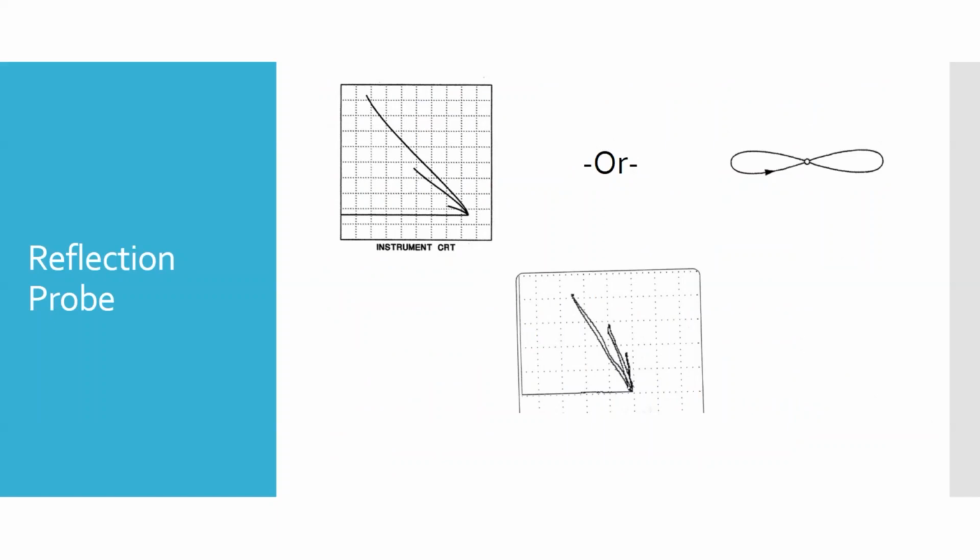And that's why we use a reference standard. So before you go test your airplane, before you go test your wheel, before you do your fuselage skin to check for cracks around rivets, before you look for cracks in the bead seat of the wheel, you have to use a reference standard that has a known good area and a known bad area, right? And by comparing those known good to known bad, you can get an idea of what kind of an indication you should be looking for when you go to your unknown part, to your aircraft fuselage, to your wheel bead, to your trunnion pin. There are all kinds of different objects on the aircraft that you may use these for.